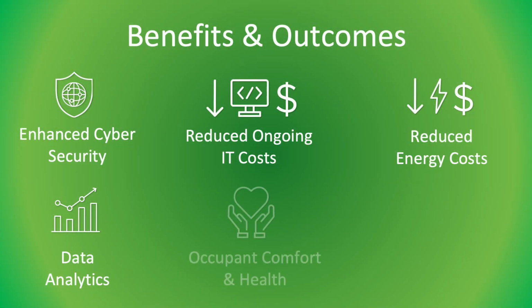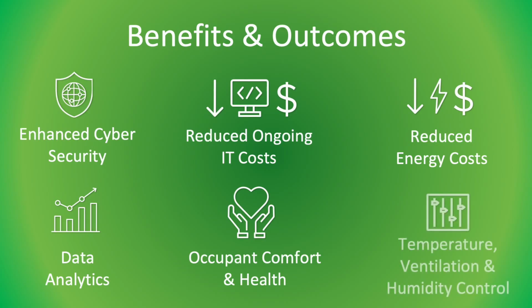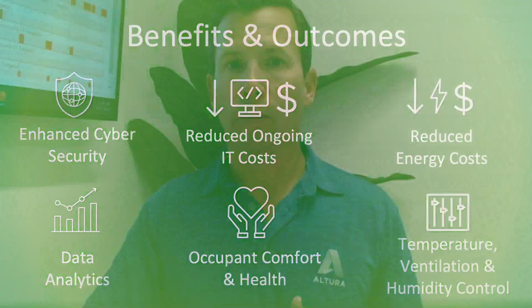It's got to go beyond commissioning. It's: show me the data that says I'm meeting energy efficiency goals, that my thermal comfort is good, that my ventilation is meeting the design intent. Obviously, occupant comfort, safety, and health is key. Proper ventilation, proper temperature and humidity control. We now have more access to those data, so we have transparency of performance.